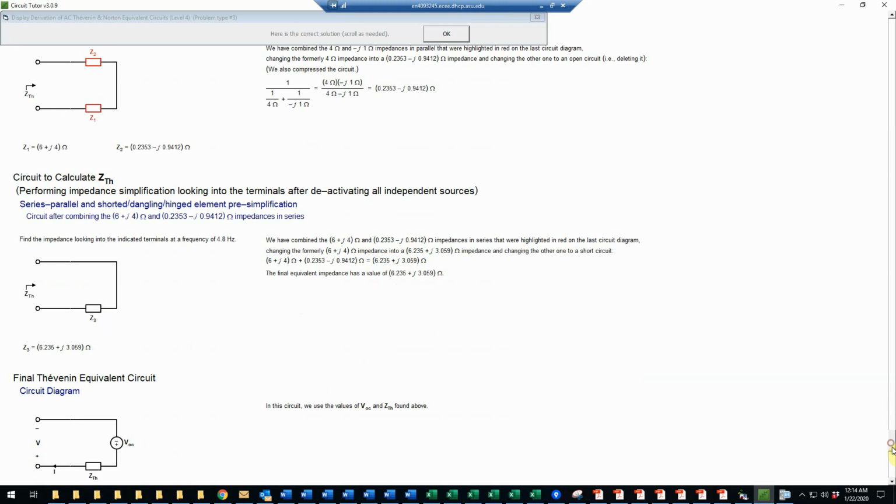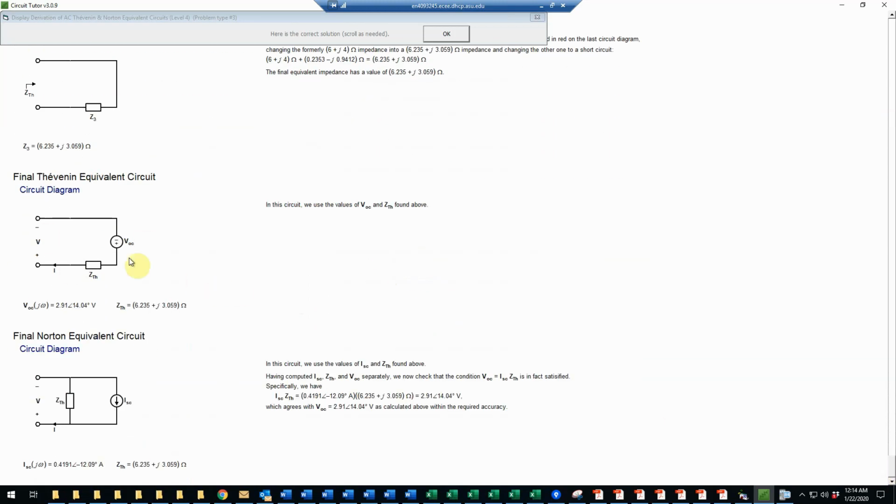So no matter how you do it, you're going to get the same final Thevenin equivalent circuit here, which has the one voltage source and the series impedance, and then the I and the V are labeled on that properly. And the VOC and the ZTH came from the above calculation, whether we did source transformations or the direct computation of VOC and Z Thevenin, or perhaps we found ISC and divided VOC by ISC to get Z Thevenin. There are various ways of getting those.